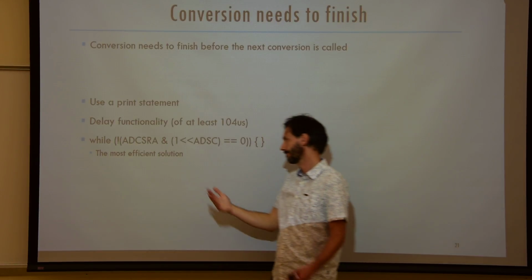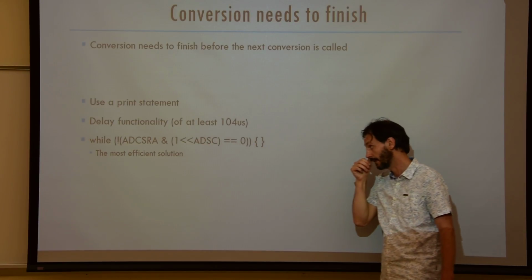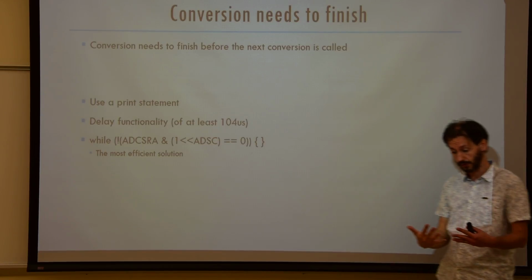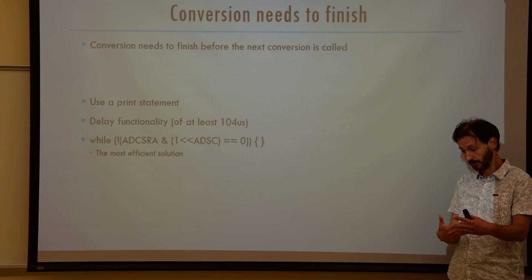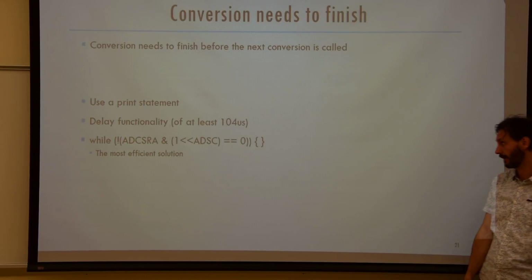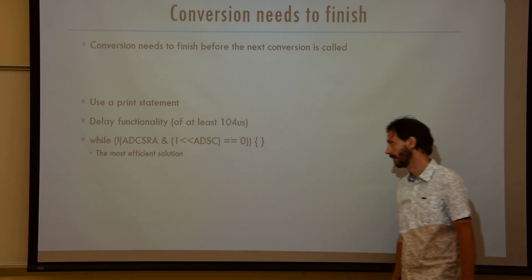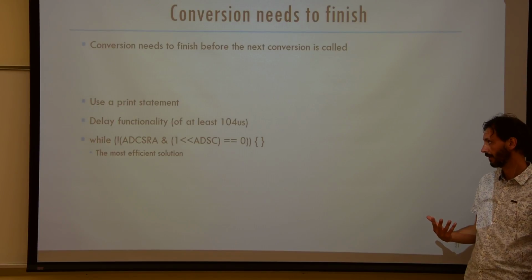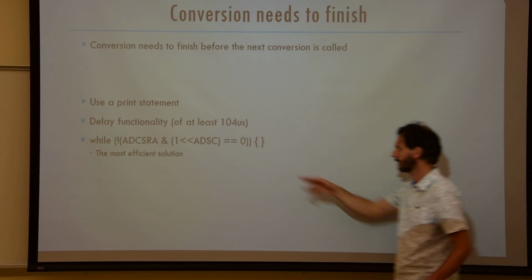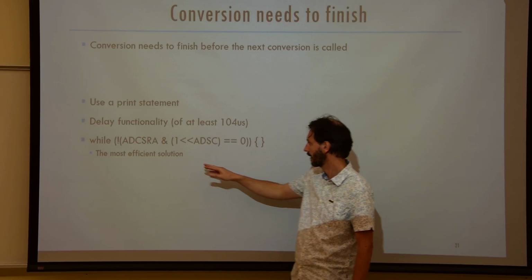But actually, what you can do is also just implement a while loop here. So it's blocking, but you just have to wait. If your program requires you in your next instruction to read that high-level register, then it's probably better to just wait for this little bit of time and then go on with your computations, rather than trying to figure out whether another computational task could take some of this time to operate. Of course you could do that, but that's not how we will be proceeding here.